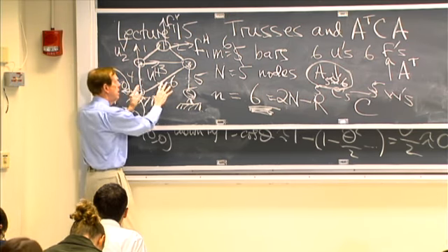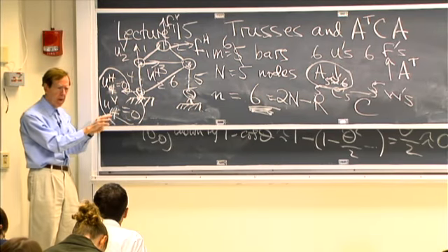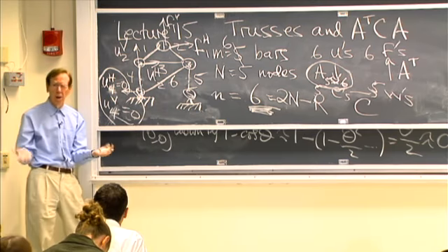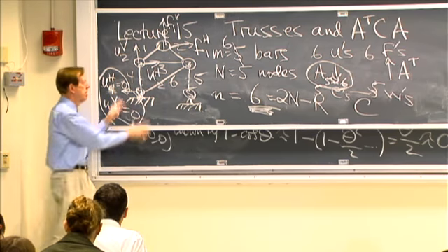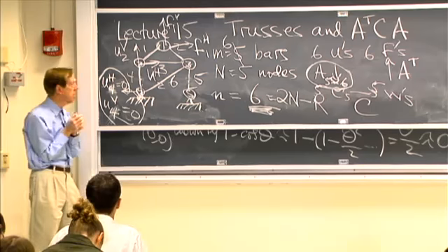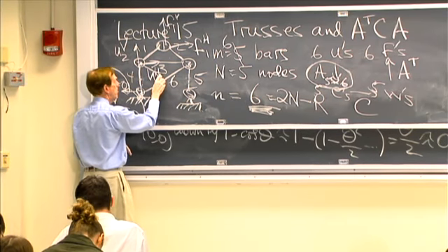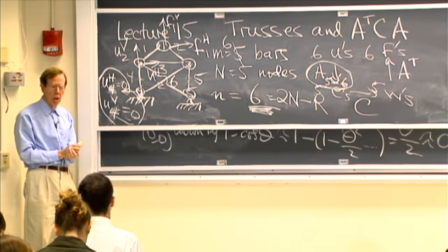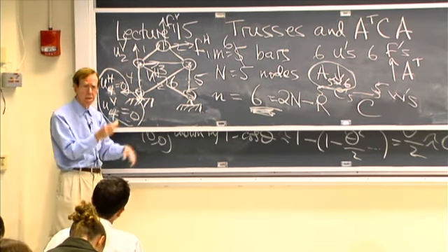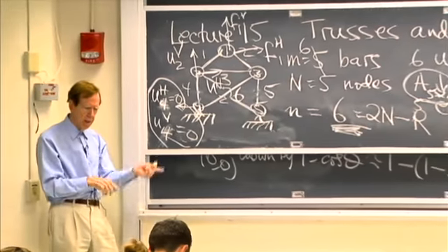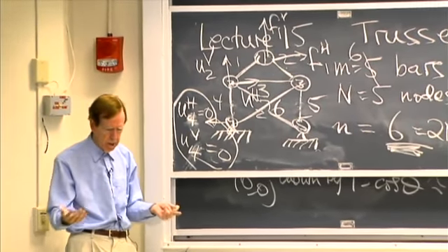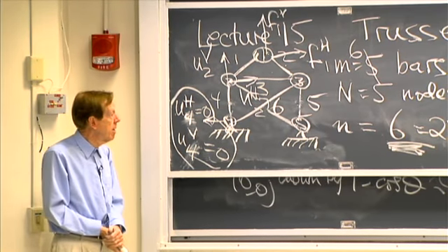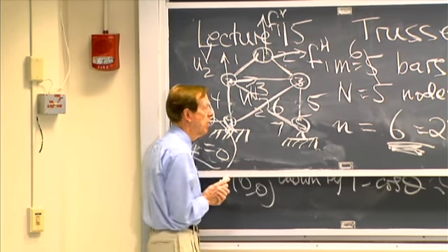I haven't written down the matrix, but I'm really calling for engineering intuition here, that this truss is now stable. And of course, I can make it even more stable by adding a 7th bar. When it was 6, I had square matrices, A transpose, then C, then A. Now I've put in a 7th bar.